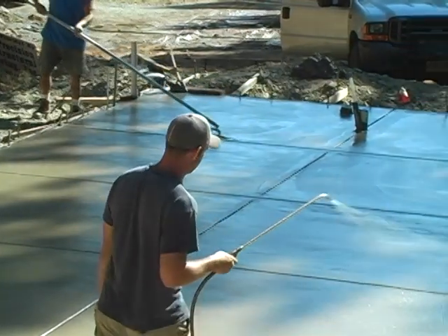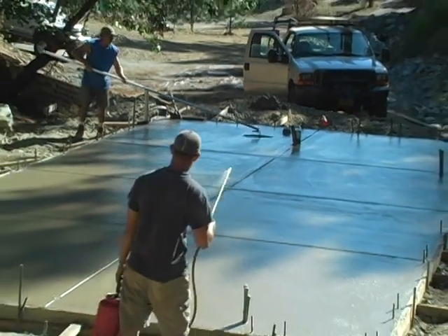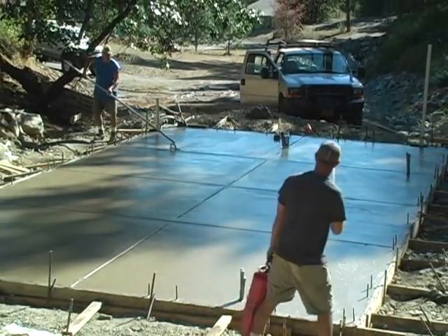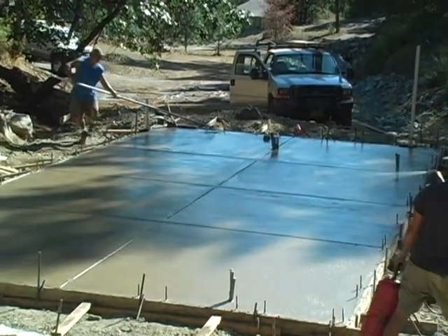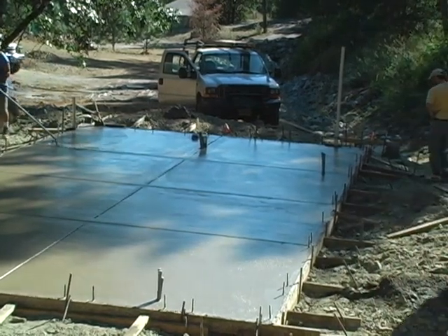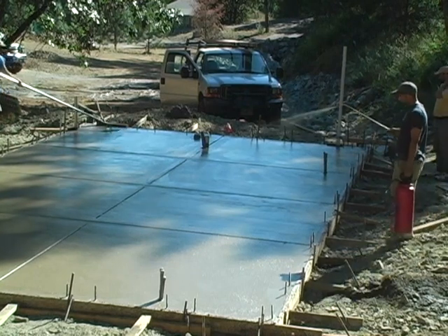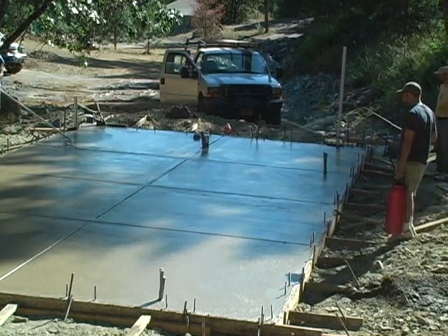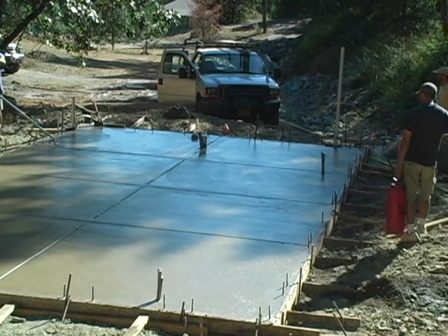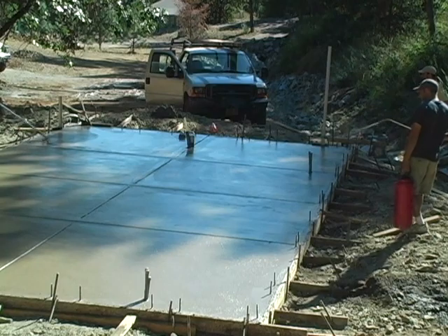We wanted to slow down the curing of the surface of the concrete so we can continue to work it with the trowel, and then also later we're going to be doing some stamping. So we're using what's called con film. We just spray that on top and trowel it in, and it slows down the whole process, and it leaves the surface much more pliable for a longer period of time. So if you're going to be doing any significant troweling or stamping, then this is a really important way to slow down the cure.